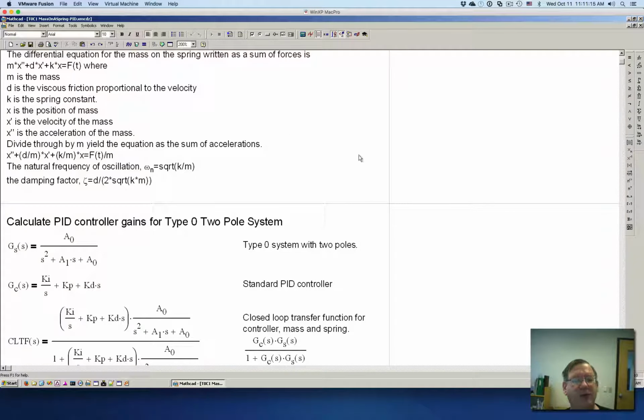One other thing I'd like to point out is that when you're designing a system, viscous friction can be a problem. Normally on a shock, you have an orifice where you have losses due to fluid moving through the orifice. And what these car companies are doing is using a magnetic oil where they can change the viscosity, so that there's more force, or the damping factor goes up, as the oil goes back and forth through the orifice. But there's a problem with that.